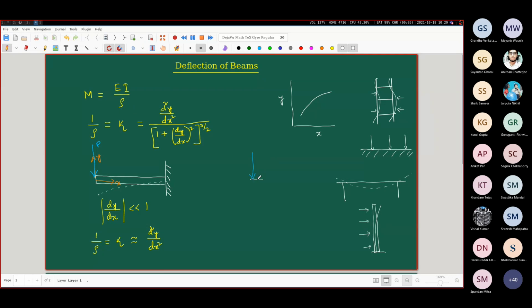that this is the undeformed shape. But after this thing has been pressed down, it will look like this. Okay, so a very complicated kind of deflection takes place at this point. And the kind of theories that we are doing, which are gross macroscopic theories, are not going to be able to handle the real scenario which is happening at this tip. So what we say is that as long as you stay slightly away from these loads, then you are safe to use these theories.